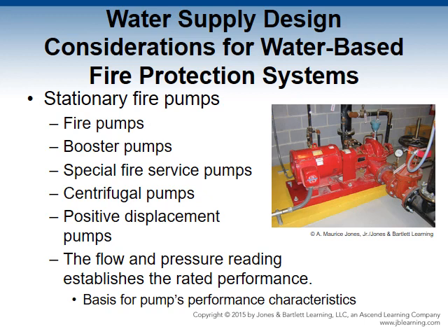Types and styles of stationary fire pumps. First, you have a centrifugal pump that creates pressure by drawing water into the center of a precision manufactured disc-shaped piece of metal called the impeller, basically consisting of what is known as the eye, vanes, and shrouds. By far, the centrifugal-type pump is the most widely installed stationary fire pump. It is available in different styles, including horizontal, vertical, split case, end suction, vertical inline, and vertical shaft turbines.